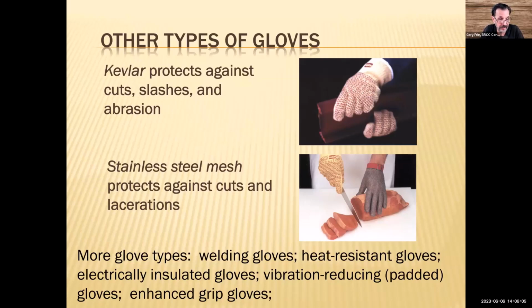There's electrically insulated gloves that electricians would use, that protect them from being electrocuted when they're working on high voltage electricity. And with those gloves, they're very fragile, so they'll use a thin leather glove over top of the rubbery electrically insulated gloves to protect them, because you can't have any flaws in that rubbery glove at all.